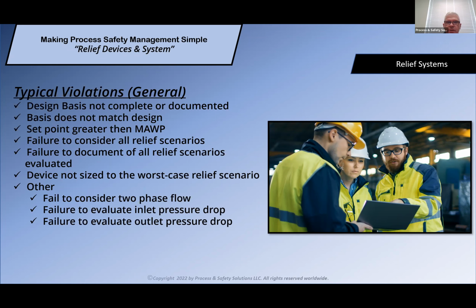You need to make sure that you understand what the media is that's going to be going through that relief valve for each scenario. Failure to evaluate inlet pressure drops, must evaluate it regardless. Failure to evaluate outlet pressure drop, must look at it to see whether or not that becomes an issue in relieving properly or not.